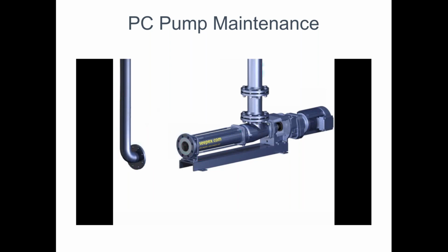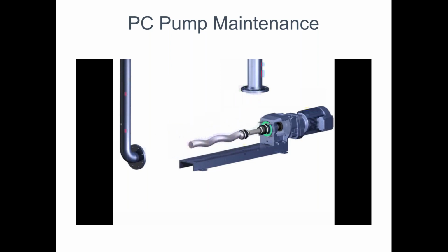You had to disconnect the discharge piping, disconnect the discharge branch, twist off a tightly compressed and fairly heavy stator, disconnect the suction piping. The suction housing had to be pulled forward after being disconnected. You'd have to pull back this elastomer sleeve or boot and knock out a pin just to remove the rotor. Then you would have to rebuild this pump altogether again. This might take 2 to 3 workers and perhaps a full day's work.